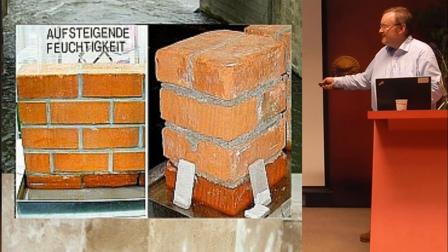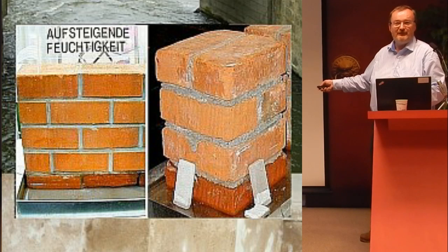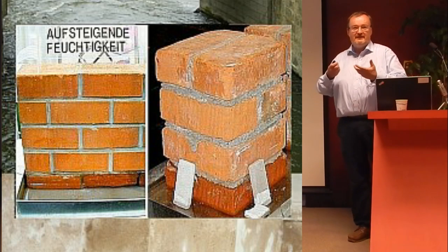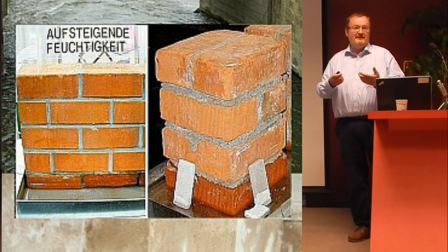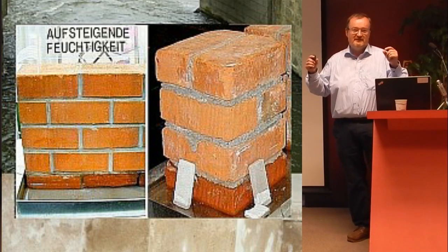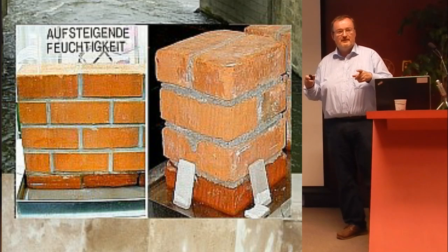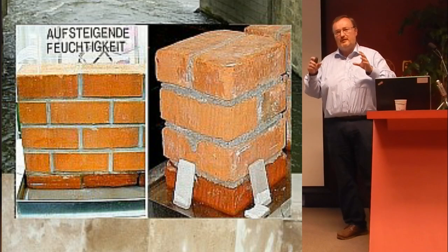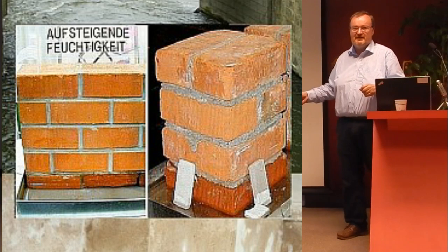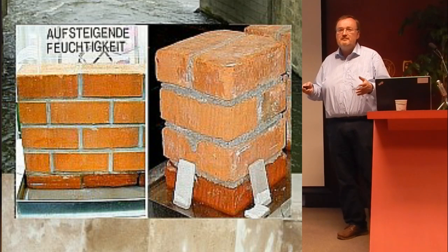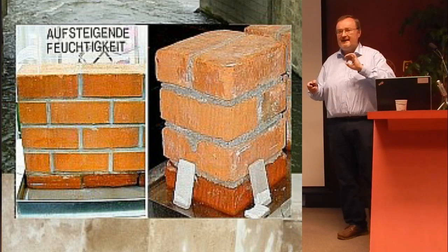What happens is the first layer of masonry will be wet, because by capillarity it takes the water in. But then comes the mortar, and the mortar has much bigger pores. The porosity of the mortar is much bigger than the porosity of the stone, so there is no chance at all for a capillarity effect, because bigger pores will never suck any water from smaller pores.